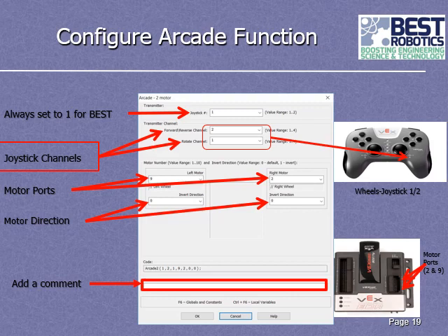The next thing we're going to have to do is pick what ports your motors are attached to. And this should match what you designed earlier and put in that configuration pop-up. When you hit the drop down for the left motor, you'll see something that says left wheel, so you'll just pick that, and it happens to be the description for motor port 9.